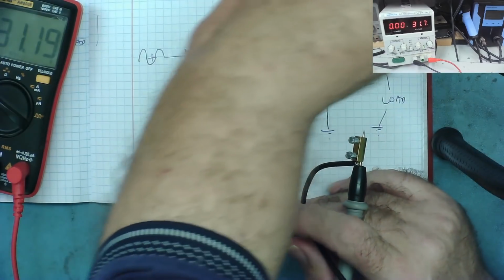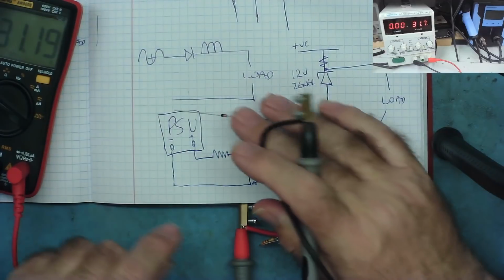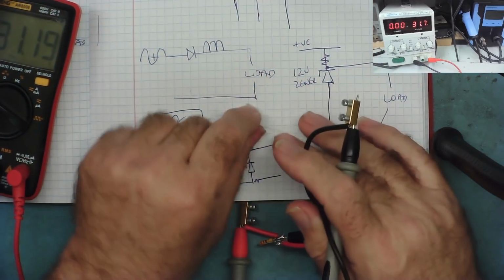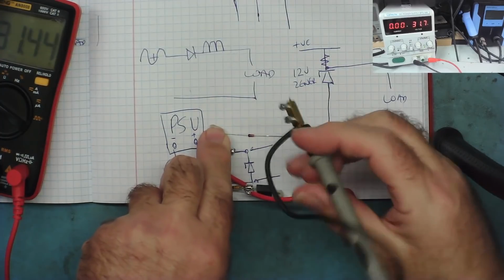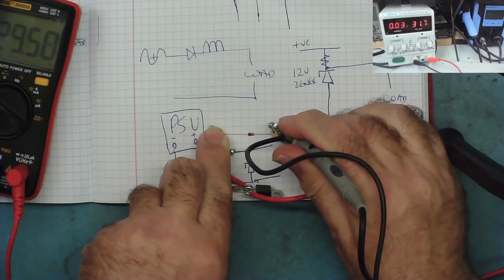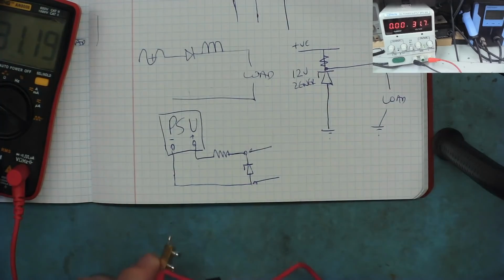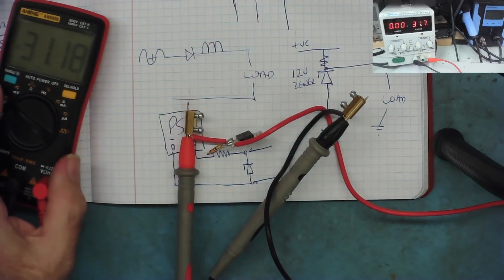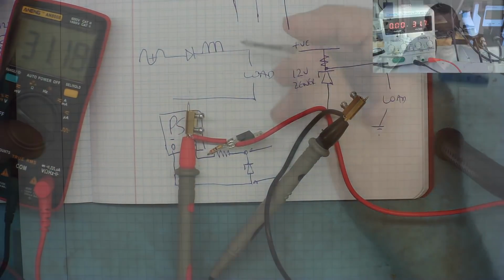And we'll just try now one more. This is one of the small ones again. So 27 volt Zener. So again, we'll just measure it in the correct direction this time. The Zener voltage from here to here, 29. Okay, so we can test the Zeners with our little short circuit finder, which is now even slightly more amazing than it was before, yeah?